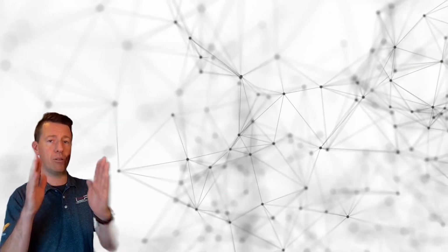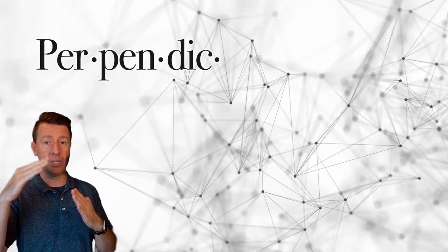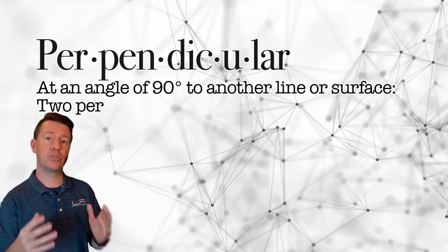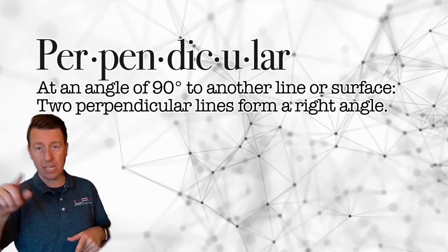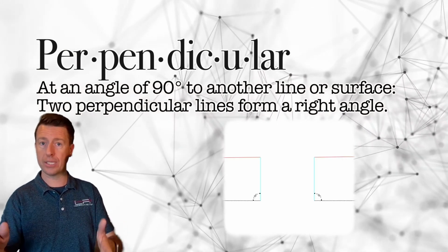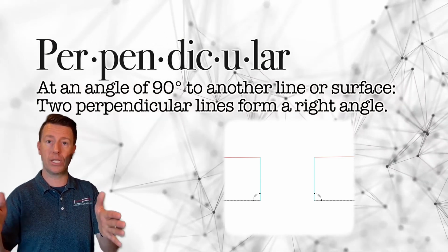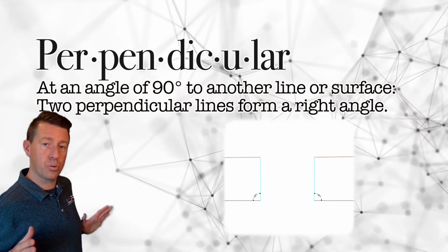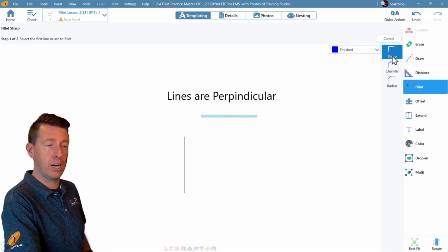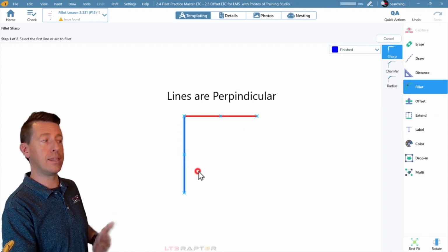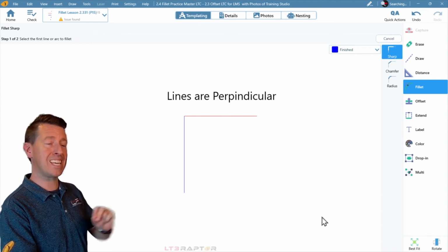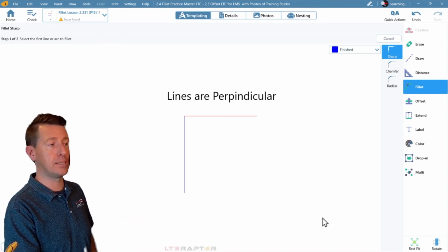We talked about parallel lines. Let's talk about perpendicular lines. Perpendicular lines will create a square corner. In some construction projects, you need to create intentionally a perfectly square corner. A range opening would be a common example in the context of a countertop. I want each of those front corners to be nice and square, right? But there's a gap in between these. Again, fillet. I'm in sharp fillet. Pick one, then the other, and it creates a nice closed corner. It closes the gap between those lines.